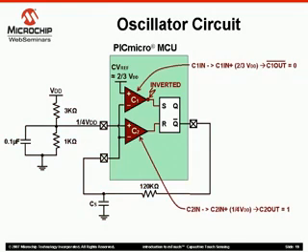We are using the comparators to create a window of operation. If the voltage across CS drops below 1/4 VDD, the output of comparator 2 will go high. Looking closely at comparator 1, notice that the output's polarity is inverted. Therefore, if the voltage across CS rises above 2/3 VDD, the comparator 1 output will go low. Both comparator 1 and comparator 2 outputs enter into the SR flip-flop's set and reset inputs respectively.